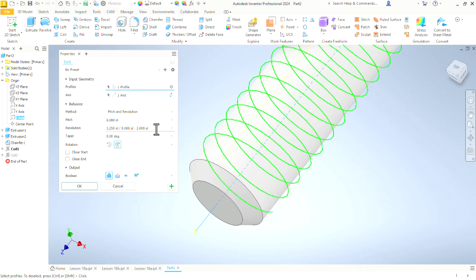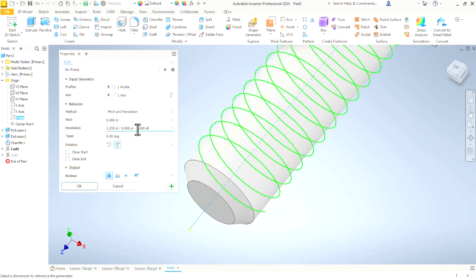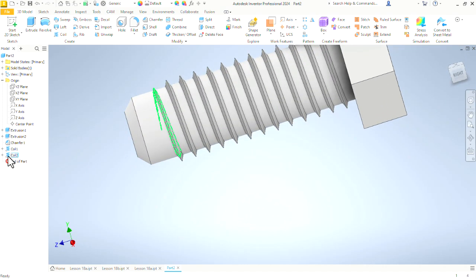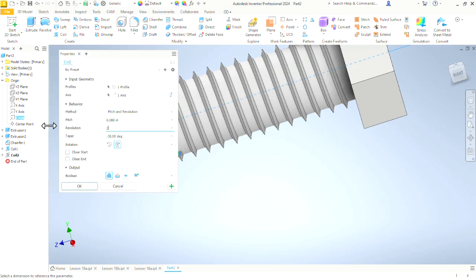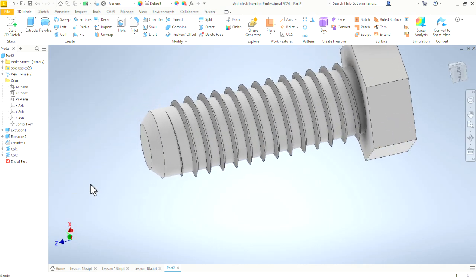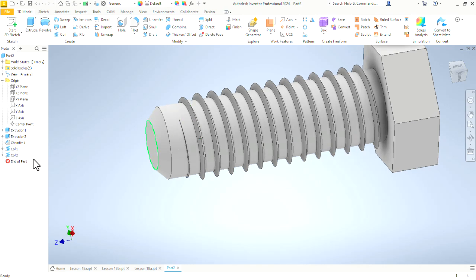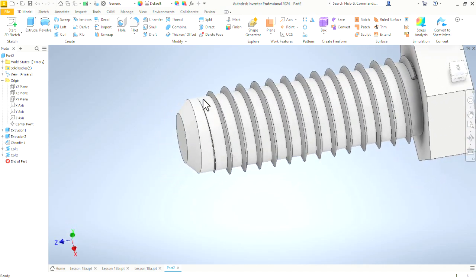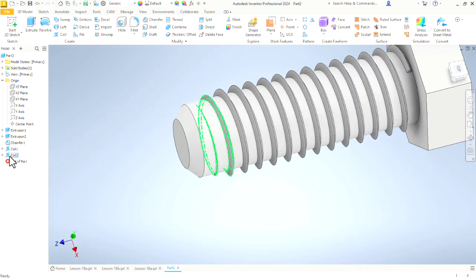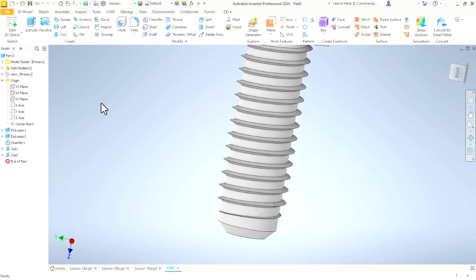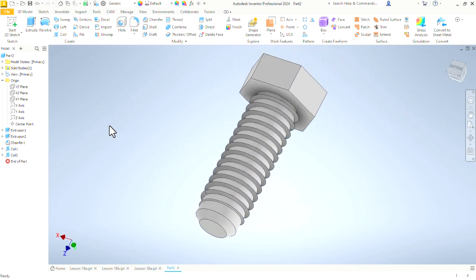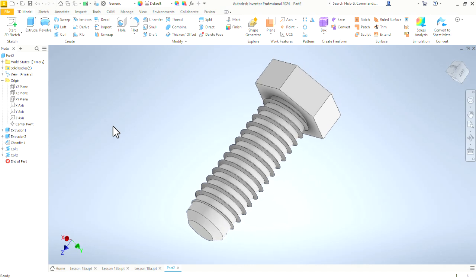What if we make this coil? Let's take another one off of there. Let's make that -3. And we stop a little bit shorter. Then we come down here. We give that 2 revolutions, maybe -20 degree taper. And we see the result that we get. It fades in a little sooner than we want it to. Let's make it -15. -15 takes it out a little bit further to the edge. Again, play with the numbers, work with it, experiment, just to see what different results you can get out of it. All right, well, that is it for coil.